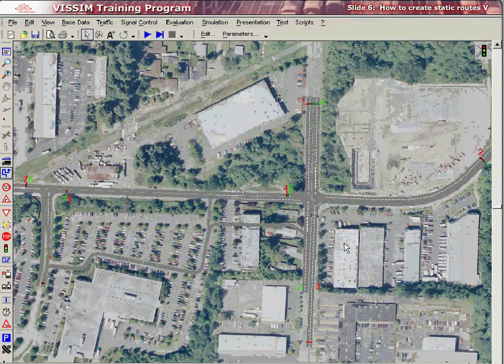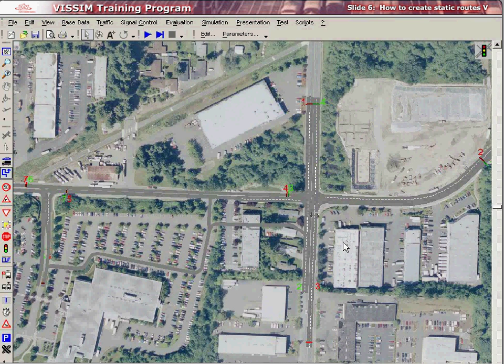Since we need to allow vehicles enough time and distance to switch lanes before an intersection, we need to start routes between intersections just after vehicles leave the previous intersection. Hence, the westbound routes through the T intersection start at the red 4, just after all of the routes from the previous intersection end. And the through route will end just after the T intersection for the same reason. Let's zoom in a bit closer to the location where this route starts.